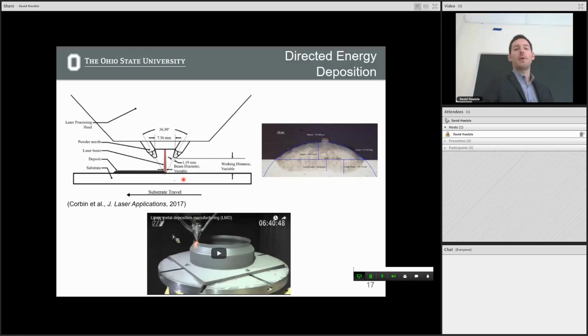And then you're blowing powdered metal through these nozzles at a pretty high rate of speed. So you have a powder jet here, a powder jet here, and then a laser, or sometimes processes use electron beams or other forms of this as well, coming through the middle. Where the jets of powder and the laser meet, that fuses the powder at that location. It melts the powder, and once the laser is removed, it resolidifies. You build up the part by making a bunch of these lines, these beads of metal powder.